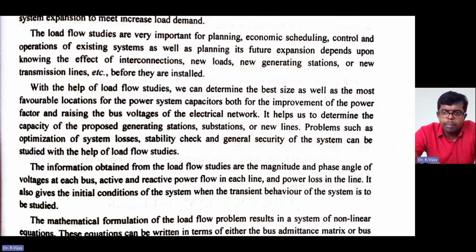So they need to maintain the power factor at 0.99 or 1. Sometimes 1, or many times 0.99 or 0.98, like that. It might be wavering. But especially for industries, they need to maintain the power factor as a constant. Otherwise, they will be punished with a penalty factor tariff.